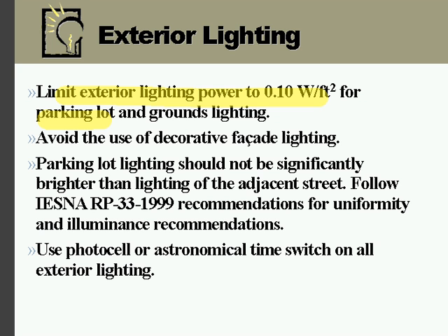Because this was intended on just energy savings, we're recommending do not do decorative facade lighting. There's a lot of buildings out there, most of them historic buildings, that look really good when they're lit up. There's a lot of buildings out there that are new and even some older buildings that actually don't look very good when they're lit up. So be very careful about how you consider whether you want to throw light onto the building. That doesn't mean that you can't have exterior lighting at the entries that are lighting stairways. Those are important areas to light for safety and security issues. We're actually talking about the decorative facade lighting. Don't do that.